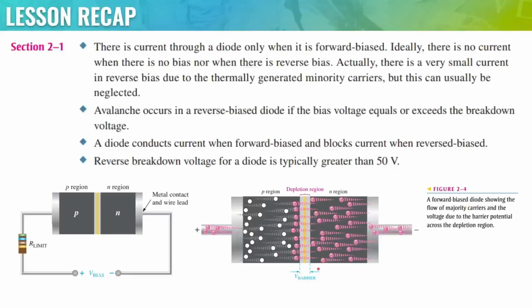As seen in this image, the electrons are going from hole to hole and then passing through the diode. Take note, holes are not actually physically there. They are just an easy way that we use to represent the lack of an electron in that region. So if you are asked to describe what's going on in this image, you can say that the electron current is moving from the N region to the P region.